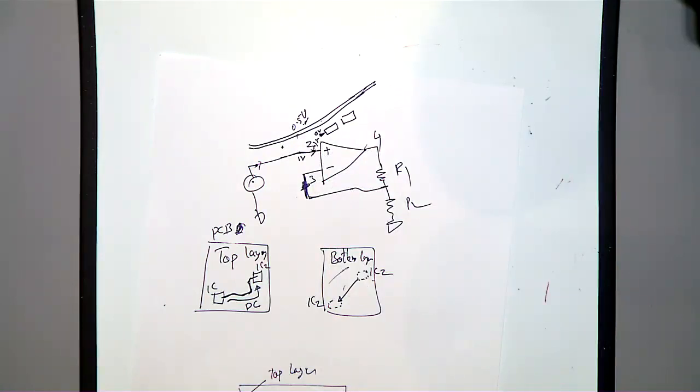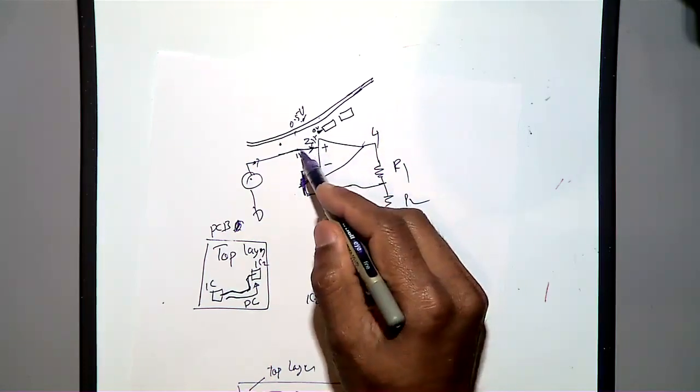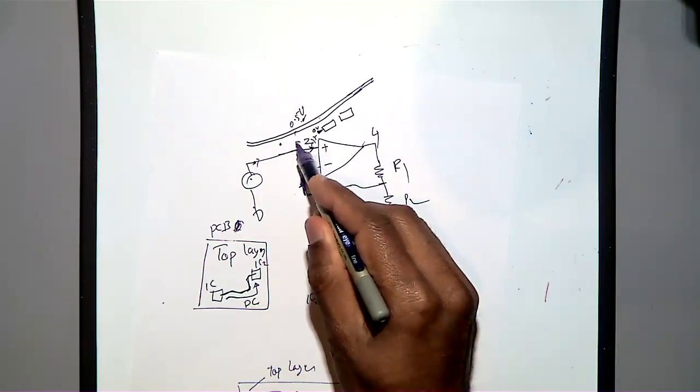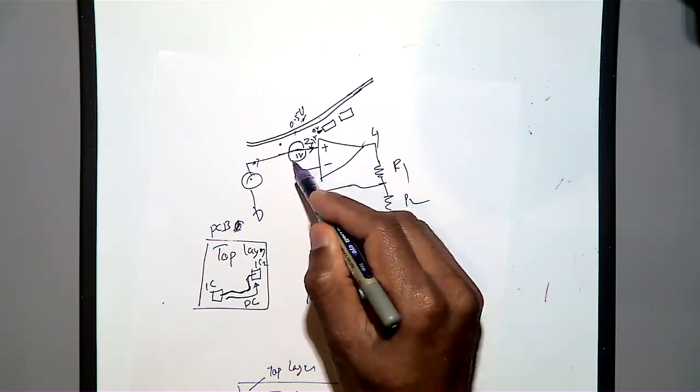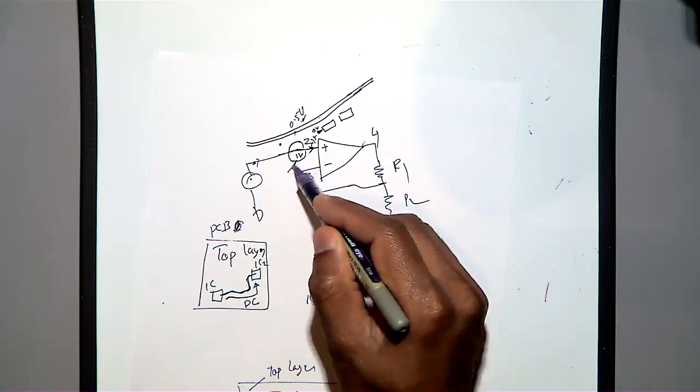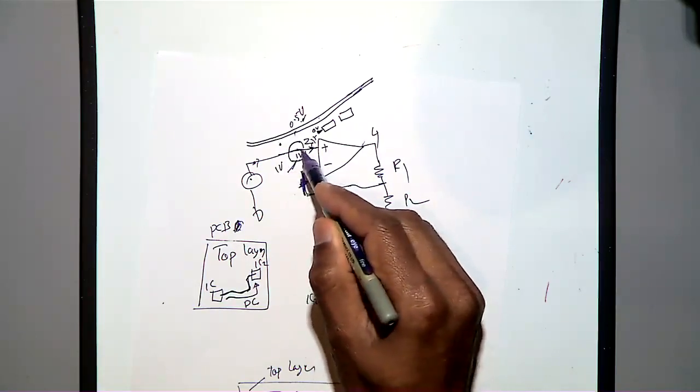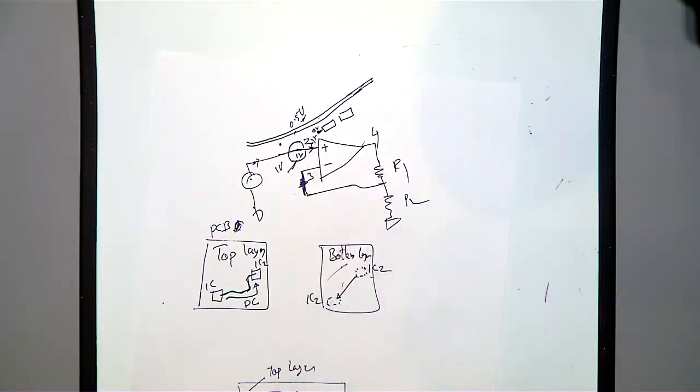Sometimes this is a real issue in some designs. If it is a very small current, how can you avoid this? For that, they will make a ring around it like this, and then they will bias this to 1 volt. So this is 1 volt, this is 1 volt, so there is no leakage. You know what I meant? So you are preventing the formation of capacitance.